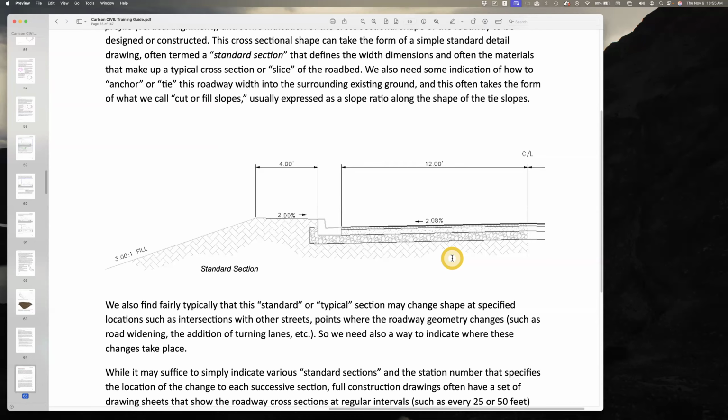And if you are going to add up the materials that are going to be needed for that road design, the computer is going to do what we used to do manually, what they call the average end area method. It drops that template at one particular spot along the alignment, and then it reads all of the areas of this information.